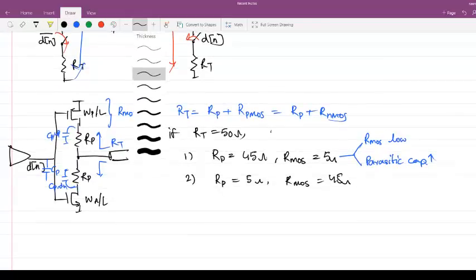So here you see two different nodes, CP up and CP down. Okay. This will introduce the data dependency, whether you are going from high to low or low to high, depending on the pattern. If I want to remove that, what can I do? So you see, I still want to use a poly resistance and a CMOS, because I need a switch, so I use CMOS. I have a poly resistance and I have a CMOS, but I want to reduce the number of nodes.